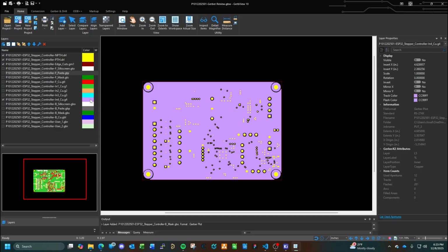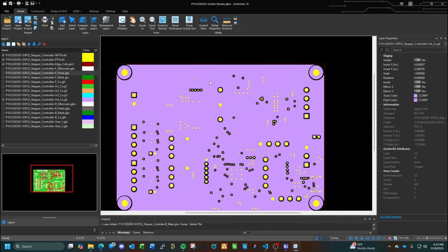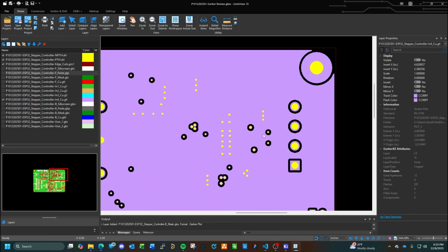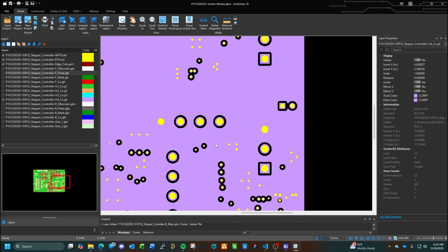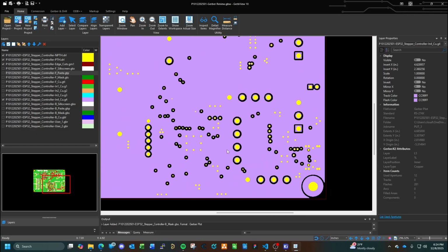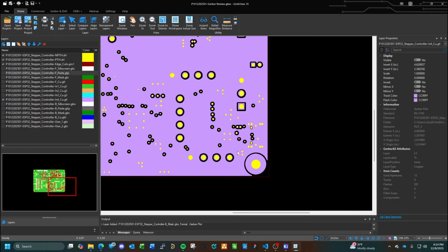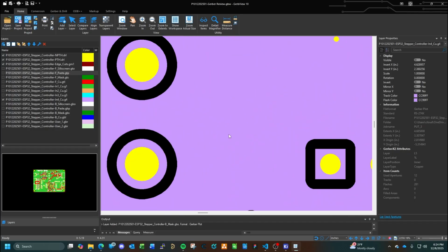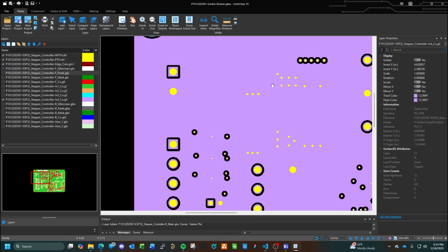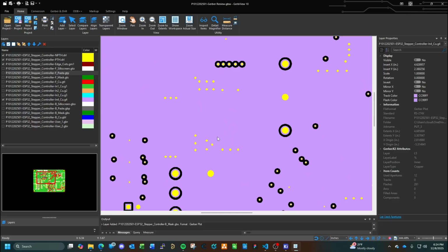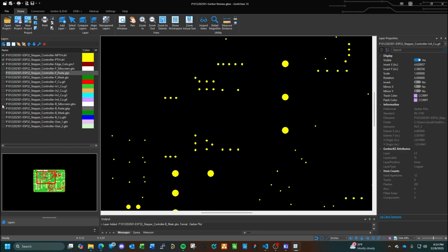It's a test point, and all we're just doing is catching on the 3.3. So again, same thing here. You're making sure that there are no odd anomalies where you're going to get a short on this plane, that everything cuts cleanly through. So that looks good. Now we're going to be looking at the bottom.